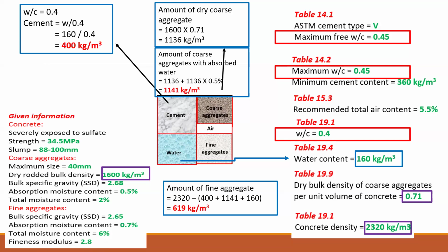We're at the end, is there no air in this place? Oh, the air. Yeah, when we consider the weight, we don't measure the weight of air, isn't it? So air is a volume percent of 5.5. That we can add by an air entrainment admixture, and we can make that. The difference between entrained air and accidental air is that accidental air is there when we mix